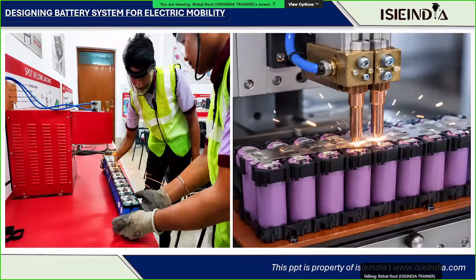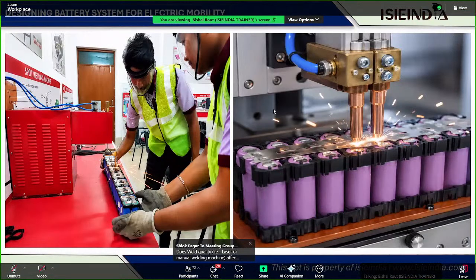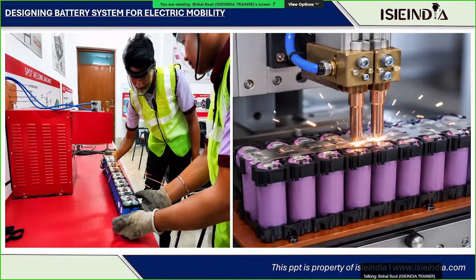Because spot welding can ignite sparks, you have to spot weld properly. You have to properly select the current and the welding time based on the material thickness. Otherwise, it will puncture the battery. While doing the spot welding, because they are in the learning phase, they have punctured certain batteries, right?